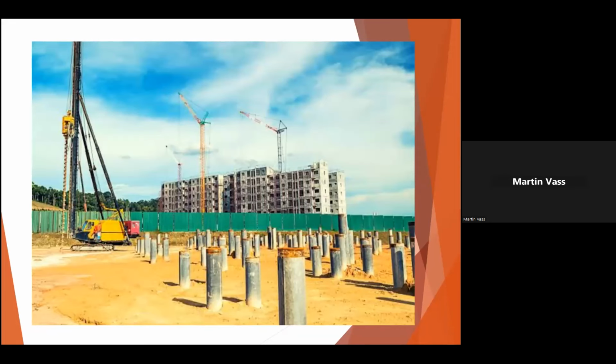So the piles either go down to what we call refusal, which is down to very hard or rock material, or they're friction piles, which depend on the friction between the ground and the pile, if there is no rock or very competent material present. So you have to work out the amount of friction you need on the pile, the diameter of the pile, the loads from the building, and work out exactly what length of pile you need to put in and the size of pile. And what would normally happen is the engineers say, I need so much kilonewton load to be imposed on that pile. The piling contractor would then design the piles and implement that operation of putting these piles in place.